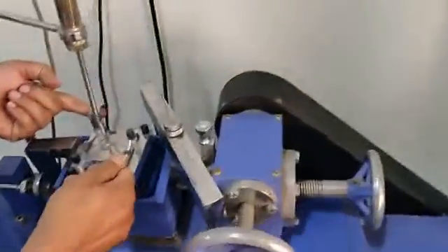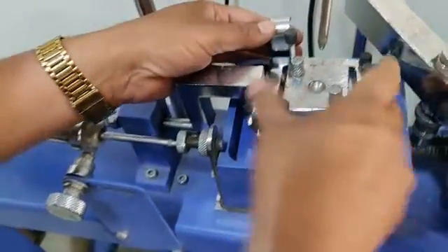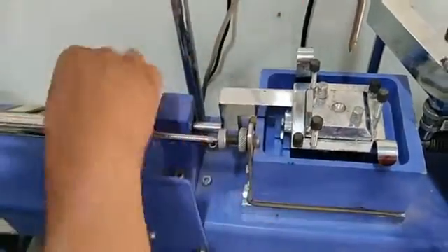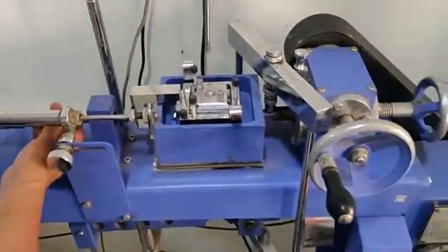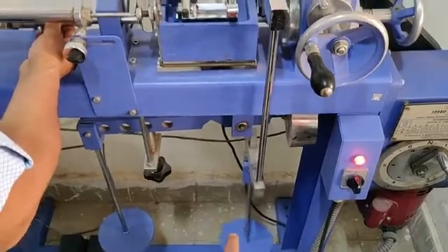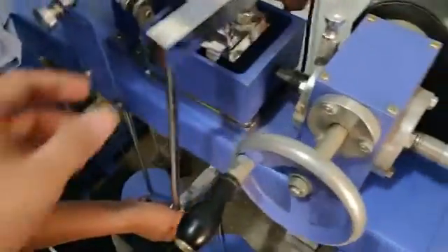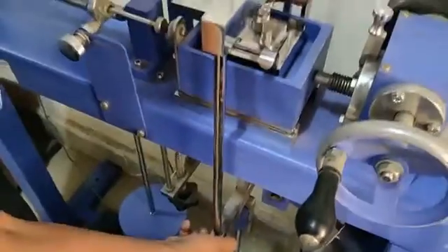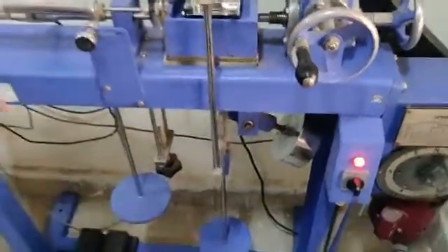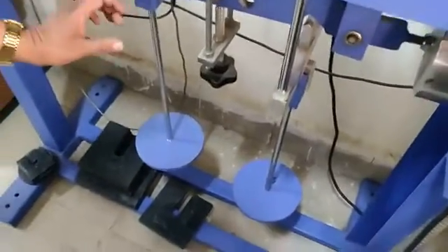Now we are going to put this whole assembly into the shear box test apparatus. So this is our shear box test apparatus, and now we are going to put this here. From this we are going to put the normal load, and we will put this on top, as you can see that we have placed. From this we will apply the normal stress on the specimen, and we have to fix the normal stress we are going to put.